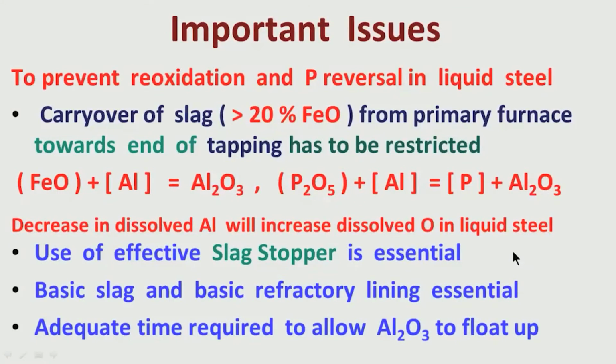So, at the time liquid steel is getting tapped, whenever slag tries to come near the tap hole, the dart will come to the tap hole and stop the slag from coming through. So, this is a way it can be stopped or to some extent controlled. Another technique is that whenever slag tries to come, a signal will be generated and the BOF will be tilted.